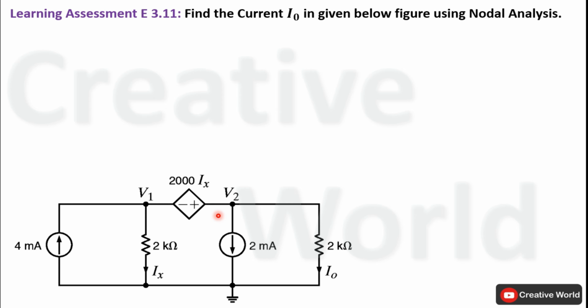First of all, if we observe, there is a voltage source inside this network that exists between two non-reference nodes. So this problem cannot be solved using the simple nodal analysis technique. In order to solve this problem, we have to adopt the supernode analysis technique.